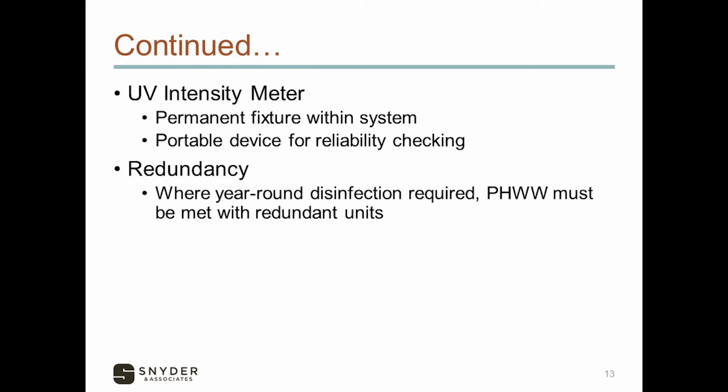Where disinfection is required for a whole year, which is somewhat rare in the upper Midwest, the design must be provided so that with the largest unit out of service, all of the remaining units would have the capacity to handle the peak hour wet weather flow in Iowa.